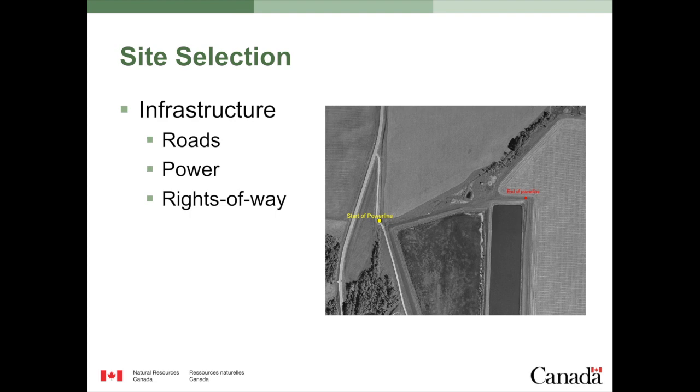A few other things, infrastructure. Because we're dealing with lagoons, they never required any power. This is all passive treatment systems. And so we had to put in power lines. So this is, again, the Beaver Lodge site. There's a $10,000 three-phase power line that had to go in from there to there, just to be able to pump water up into the field. The same thing with Claremont, the same thing with Owhatton. All had to have power lines put in. Some are single phase, that really doesn't matter, but that's something you've got to consider.